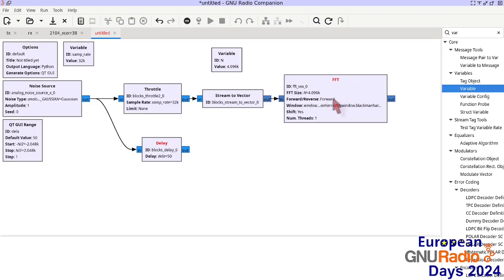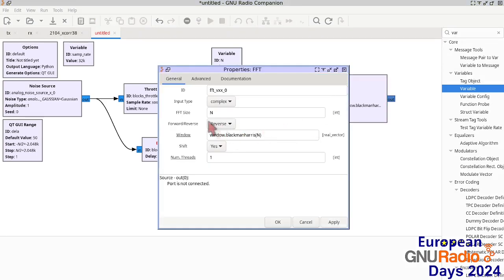The forward or inverse Fourier transform is a matter of convention, whether you're taking the time domain sample x and multiplying by exponential of plus j 2 pi ft or by exponential of minus j 2 pi ft. Depending on the field, it's one direction or the other. The only thing that matters is the IFFT of the FFT is identity, and because I know the solution in this particular case, we need to start with a reverse